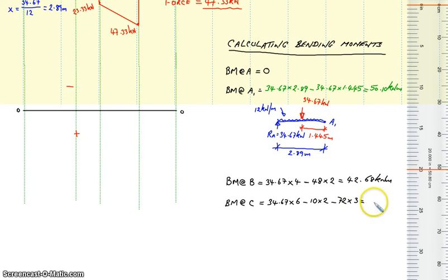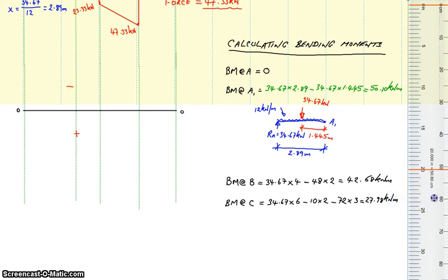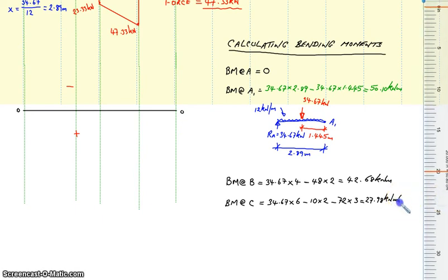And that all, whenever calculated out in your calculator, will actually show you a minus sign, but really and truly we do not have minus numbers within bending moments, what we do have is positive or negative moments. So we have the answer of 27.98 kilonewton meter, and I'm just going to shift this over a wee bit. And rather than writing that minus number, we write negative behind it, and that tells us that that is a negative bending moment.